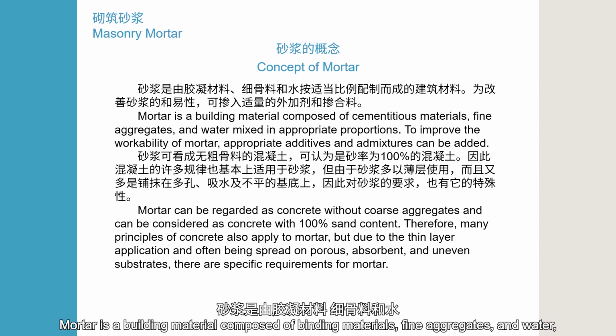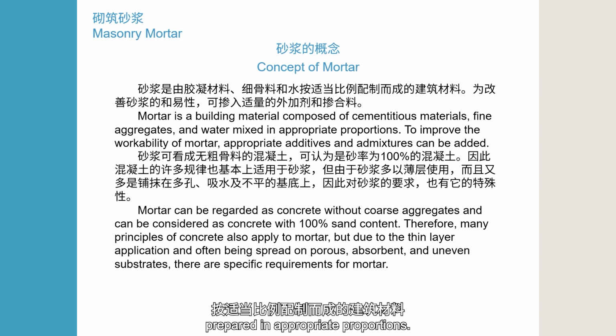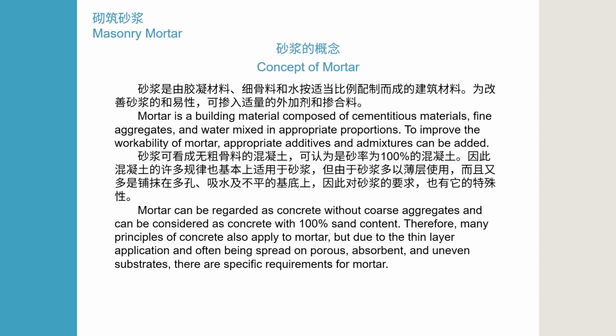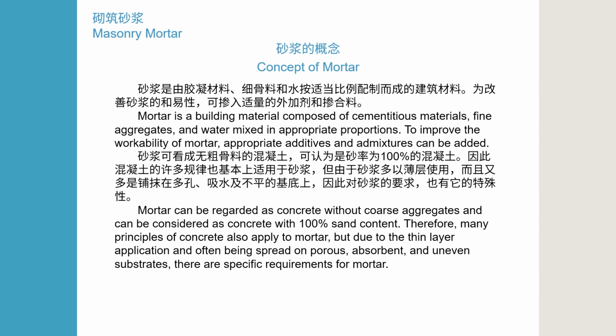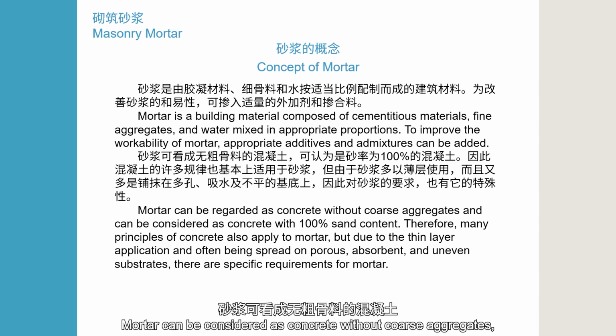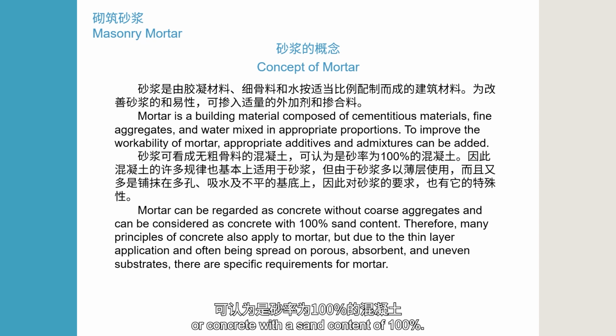Mortar is a building material composed of binding materials, fine aggregates, and water, prepared in appropriate proportions. To improve the workability of mortar, appropriate additives and admixtures can be added. Mortar can be considered as concrete without coarse aggregates, or concrete with a sand content of 100%.